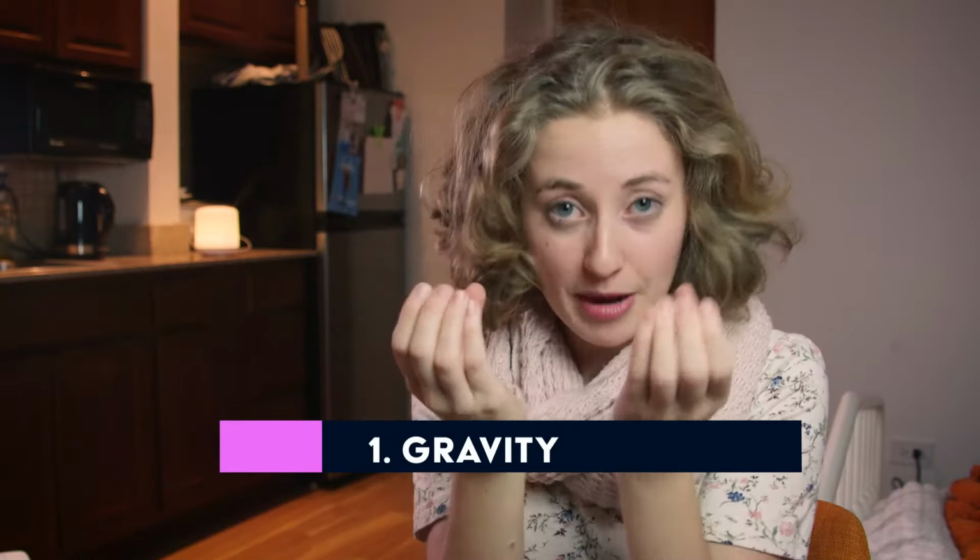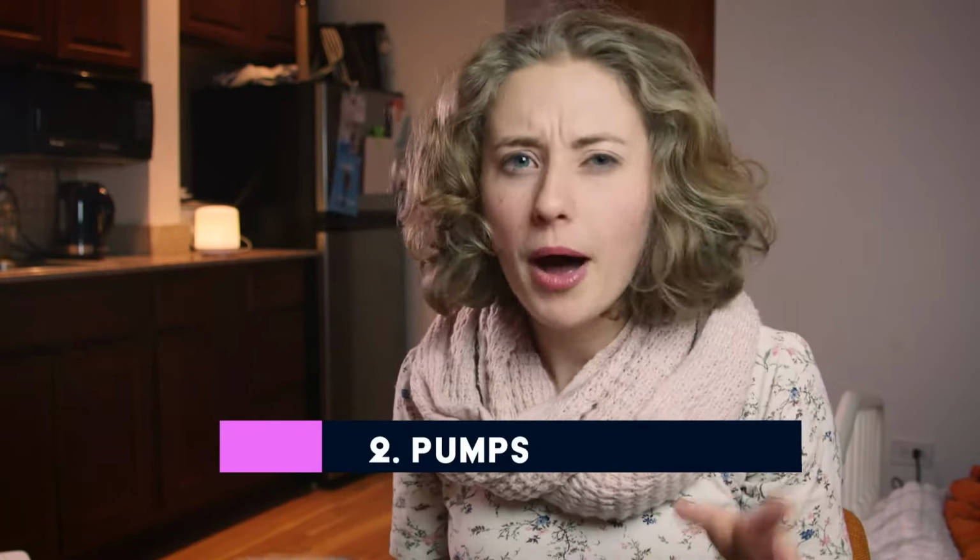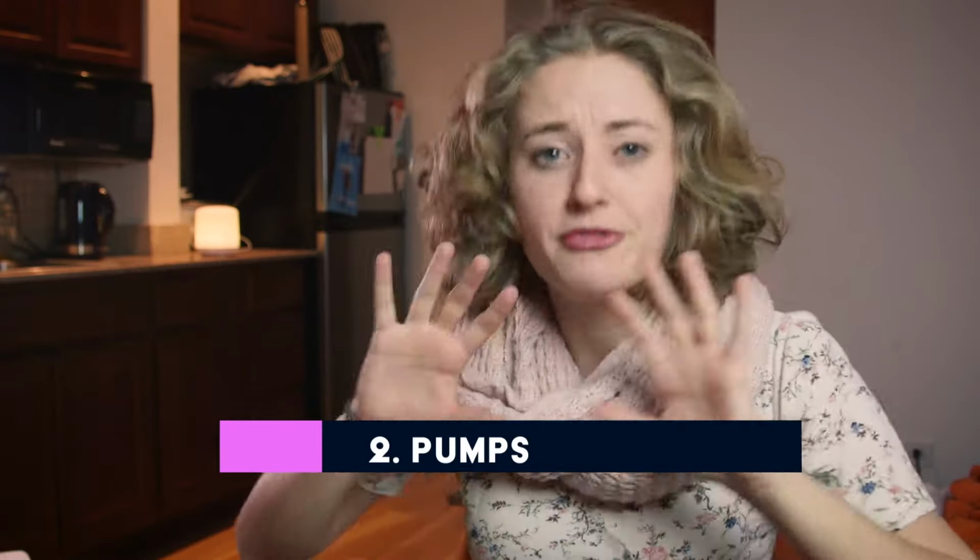There are two main things that create pressure. Number one, you have gravity. If I take my pipe and I tilt it, the gravity is going to create pressure downhill that's going to move the fluid. I could also use a pump, and what a pump does is basically just cram fluid into the pipe that's going to push the fluid in front of it and create a flow.